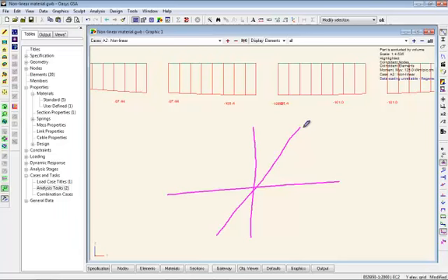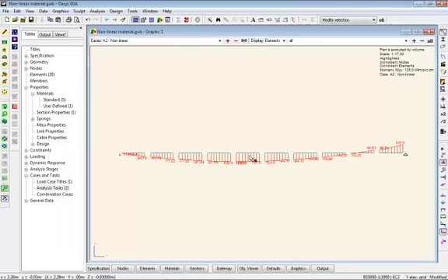Once we reach the elastic limit, we then actually get an elastic plastic stress distribution, and at the end we then get a full rectangular plastic distribution. This structure would actually be unstable in that situation, so it would fail if we had full plastic hinges forming in the midpoints of these as well as the end.